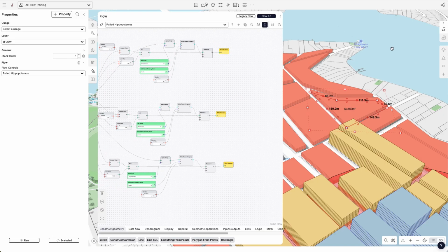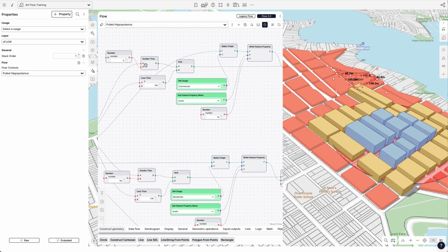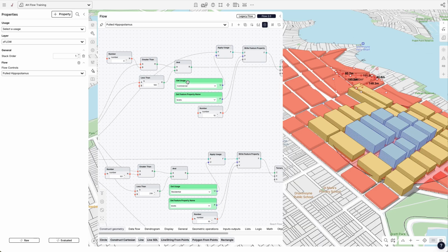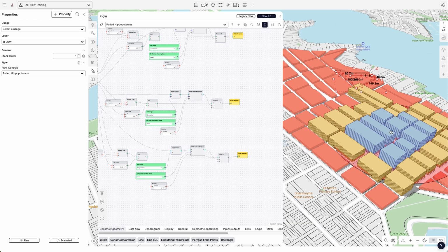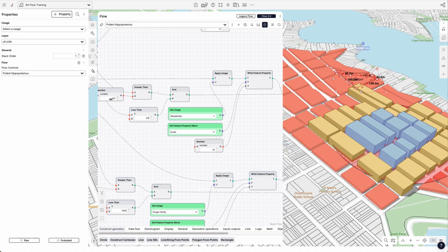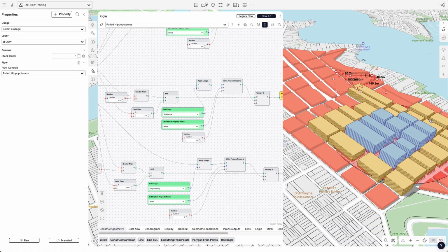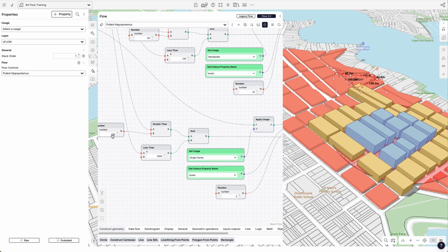And what we're doing is, because our activity center has a commercial center, the first feature that's being written is the commercial zone within the parameters defined. So if I zoom in here, I've got a greater than 0 and a less than 100. So within a 100-meter radius, we're applying the usage that is commercial, and then repeating that process based on proximity to that centroid for the surrounding medium residential usage that we have here. And that's between 101 to 220 meter radius. And finally, the single family usage is being applied from the 220 mark out to the 1,000 meter radius.